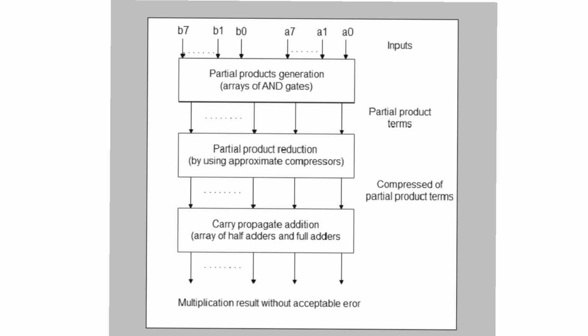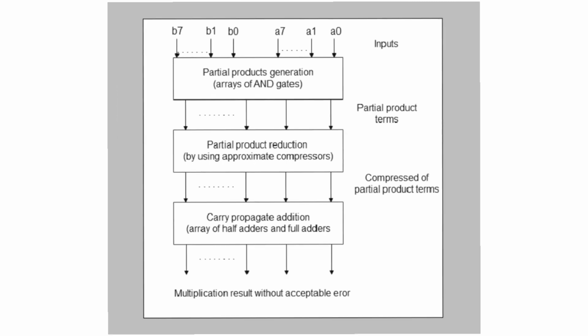After the reduction process, we add the signals or components with the help of OR gates, half adders, and full adders. Every carry is added array-wise and the sum is given in the final output, or it is added column-wise until we get the final product. This method is called carry propagate addition. The entire block is called the exact multiplier. It gives an exact output without errors.